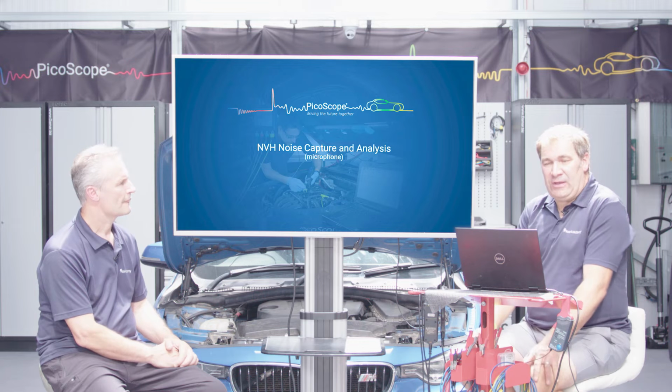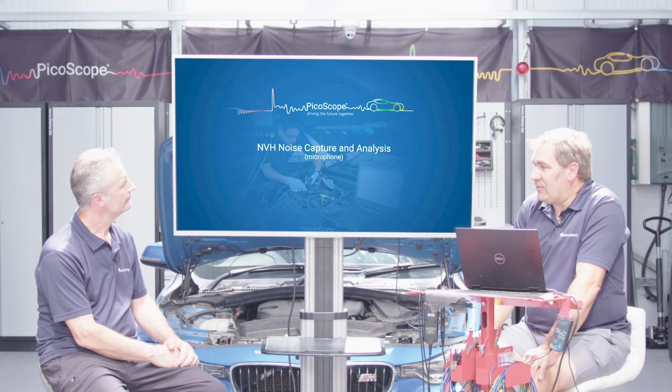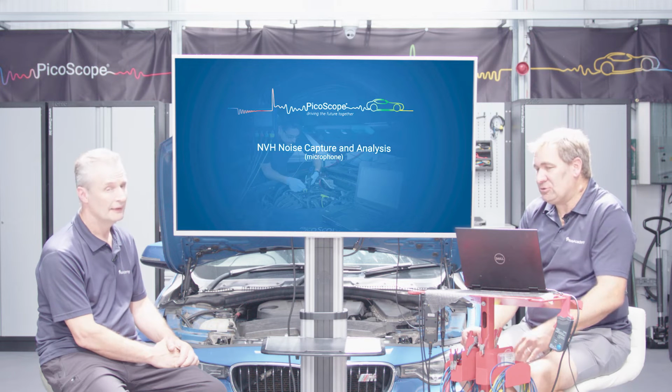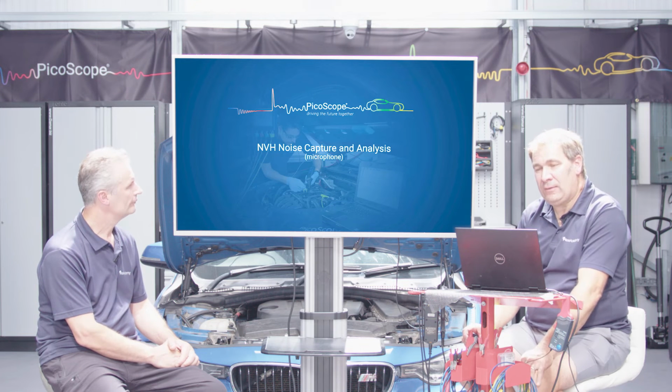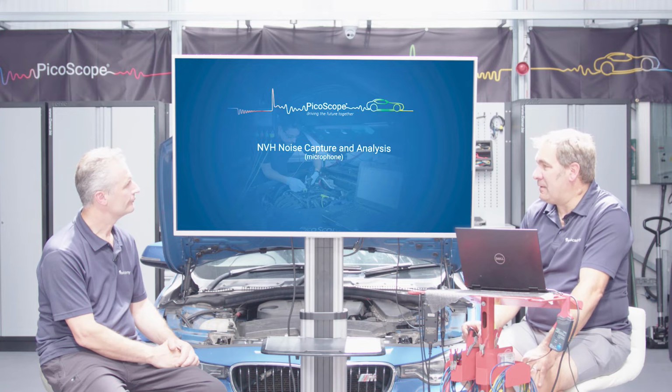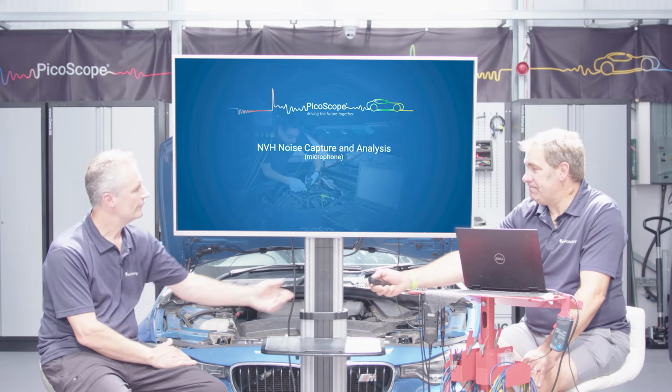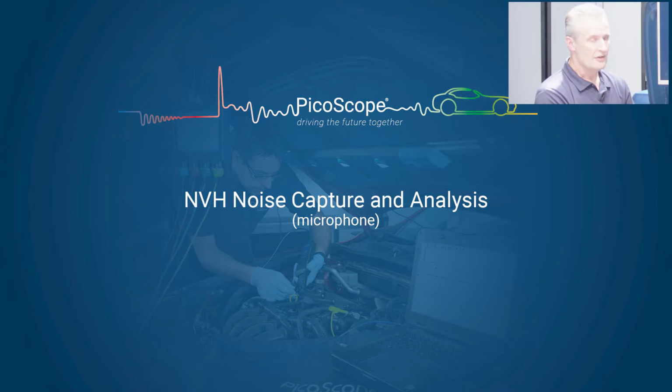Okay, so we're going to have a look at NVH noise capture and analysis, and Steve's going to take us through a little case study that he did a while ago, and it really explains just how important the use of the microphone can be when looking at issues around sound. Yeah, thank you, John. So as John mentioned, for those higher frequencies above 200 hertz, that's where we want to use the microphone. Equally, it will capture frequencies low down as well, so you get quite a bang for your buck here.